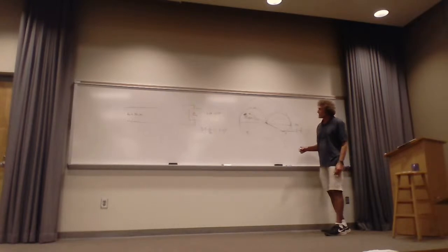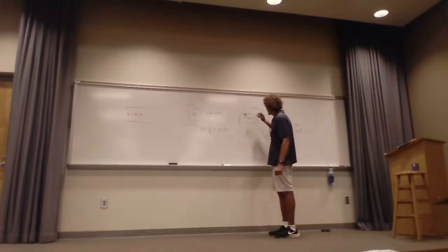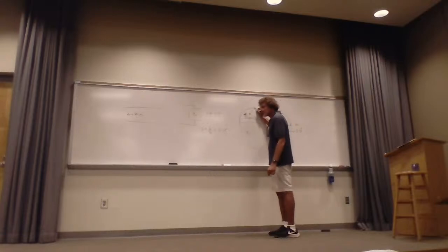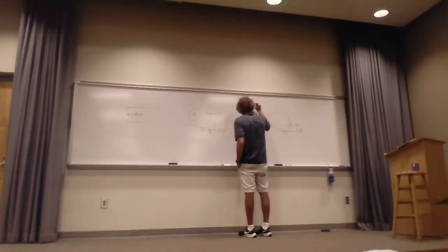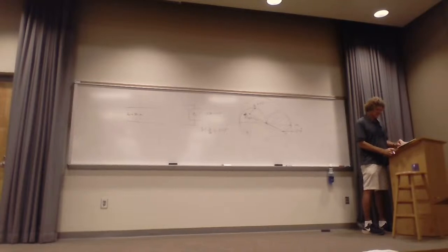Anyway, so I have 0.1 plus J 0.1. Now, if you look in your book or look at a Smith chart, and I'll give you some of these. I'll send you a rotated Smith chart and print some off. If I move from here to here on that one, I'm going to intersect this rotated circle. And it's going to have a real value, this is 0.3, of 0.1 plus J, and we're going to take a look at that. He shows this to you.